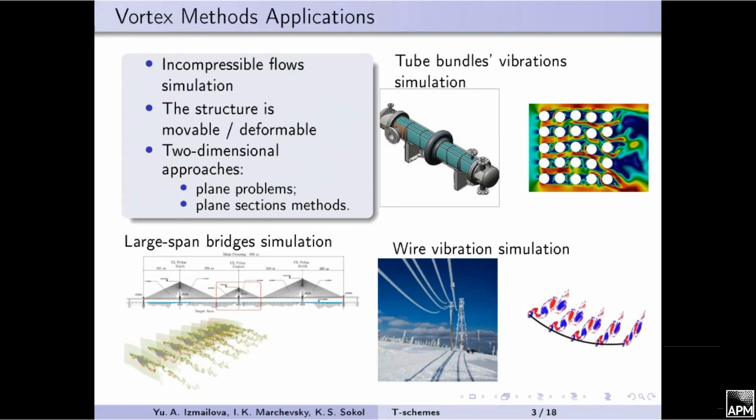The application area of the vortex method includes the simulation of subsonic flow, and quite a few three-dimensional problems can be solved using the plane sections method, where compressibility can be neglected.